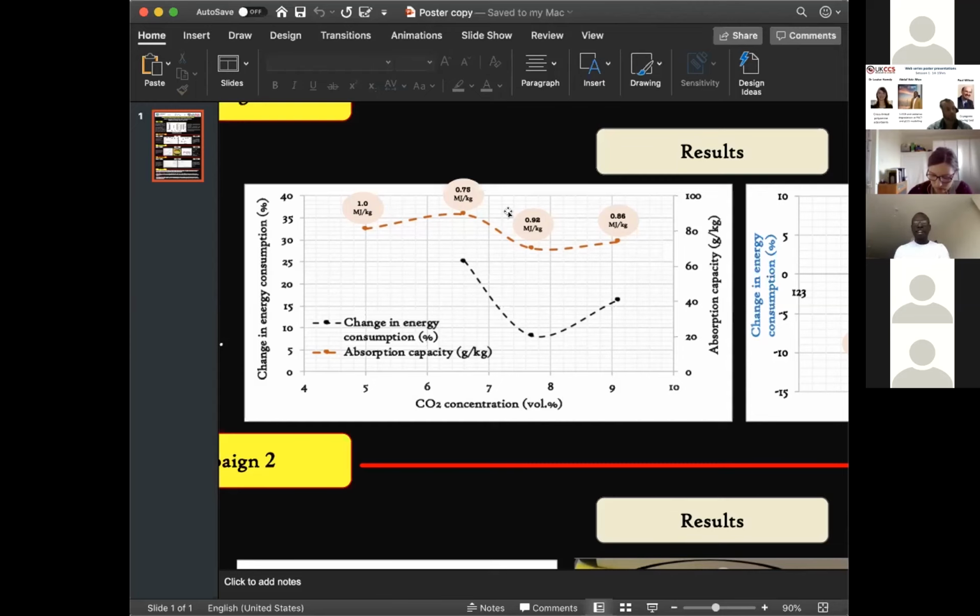If you are designing your CO2 capture facility with EGR, evidently the capacity of your CO2 capture facility will have to decrease because of the reduced flue gas flow rate into the CO2 capture facility. All right, thank you very much. Thank you as well.